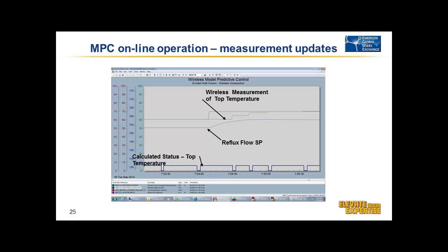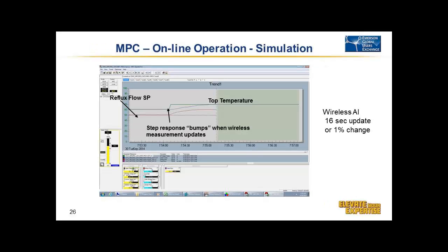despite the measurement, as you see, being quite stepwise. And this really shows the simulated value of the process output, and you clearly see that at certain points there are small bumps. That's exactly what happens at the process model update. As you may recall that diagram when I showed how the model is updated graphically, those are shifts of the process output trajectory. Another test which we performed was MPC performance.